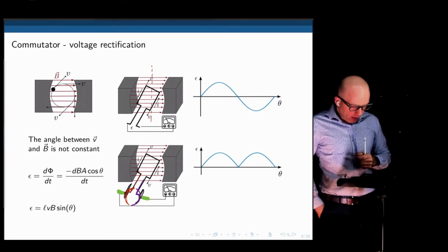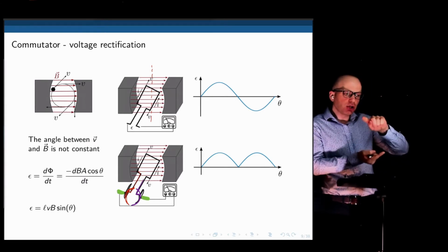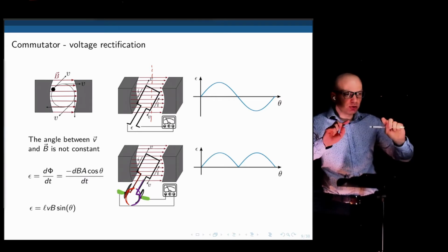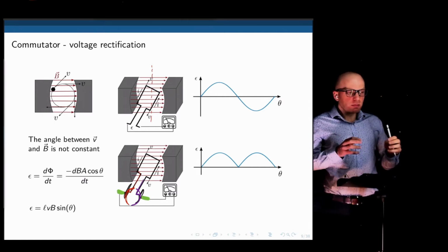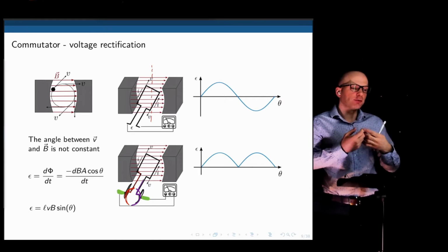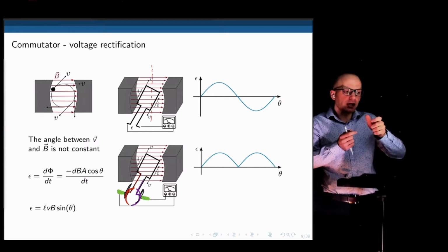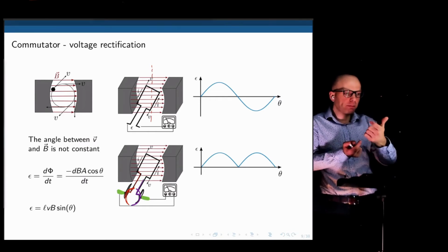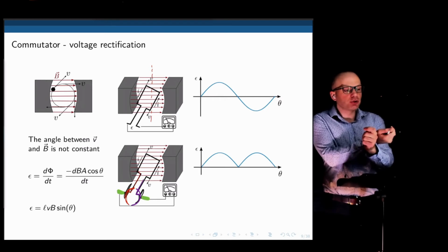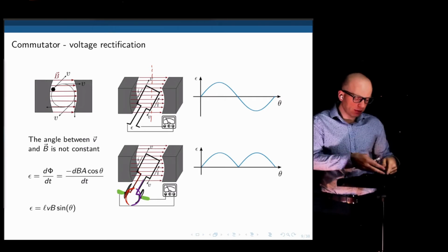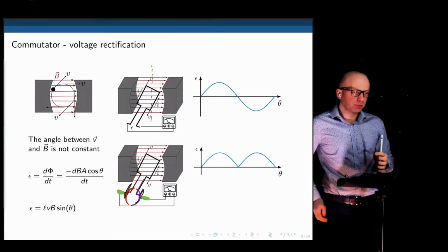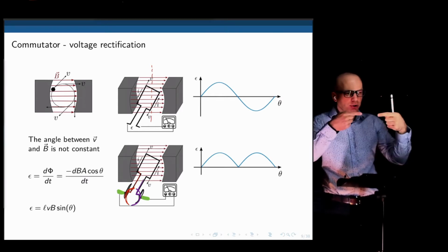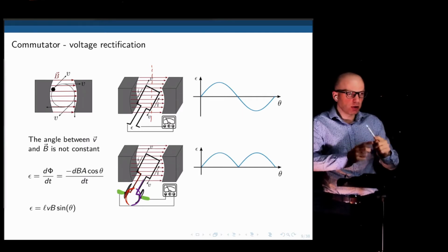And what happens now? If we do this properly, when the current changes direction, the commutators will also flip direction. We are basically connecting the collectors to different poles of this multimeter. This means that from the multimeter's perspective, we should always see current flowing in the same direction. As soon as the current flips direction, as soon as we pass the 0 EMF mark, we flip the orientation mechanically. We are flipping the orientation of these collectors, so we flip the way the voltage is measured. The voltage is then measured, from the multimeter's perspective, always in the same direction. And that's the role of these commutators here. They typically have carbon connectors with little springs that push against moving rings. In this case, each ring would be 180 degrees.